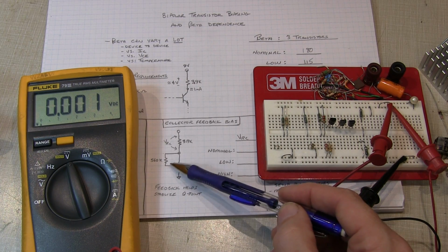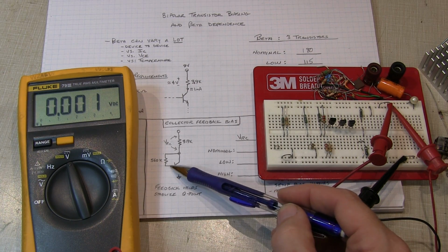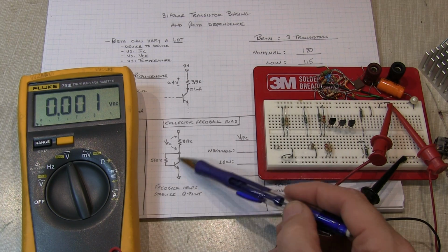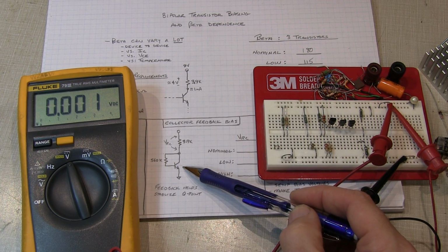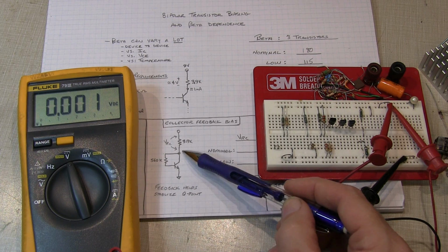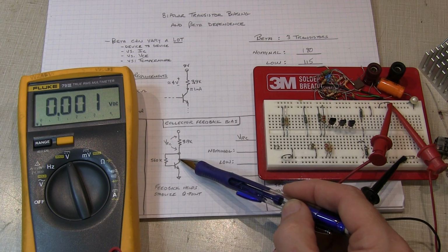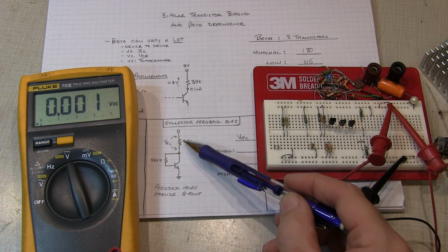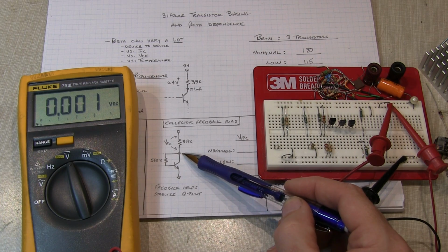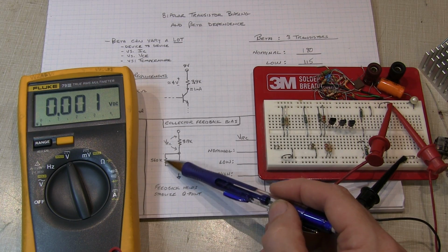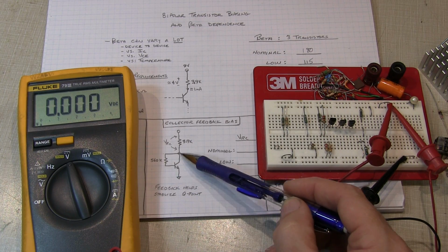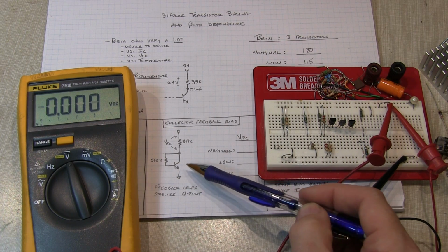Let's say for a given base current, therefore a given voltage across this resistor, we're going to have everything kind of stable. If the beta were to increase, that increase for the given base current would cause the collector current to increase, which would pull this node down because it would drop more voltage across the collector resistor. As this node gets pulled down, that would reduce the voltage across this resistor, thus reducing the base current. So it would tend to limit how far down that gets pulled.